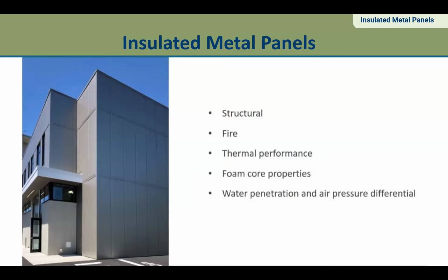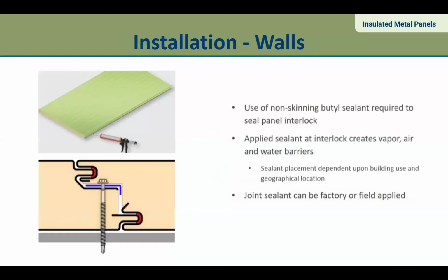Enhanced thermal properties. And water penetration and air pressure differentials are accommodated by these as well. So every time insulated panels are installed on a building, a full set of shop drawings and structural calculations are provided to address all of these concerns with structure and pressure differentials.